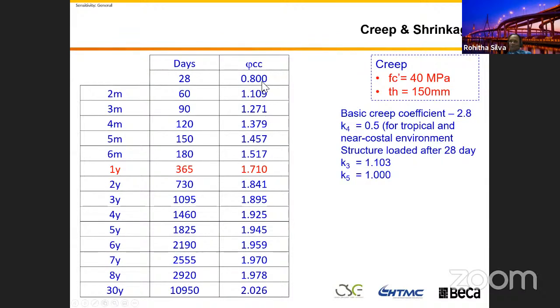This calculation shows that after 30 years the creep factor increased to 2.026, or else increased the initial strain by 200%. I just want to highlight this.